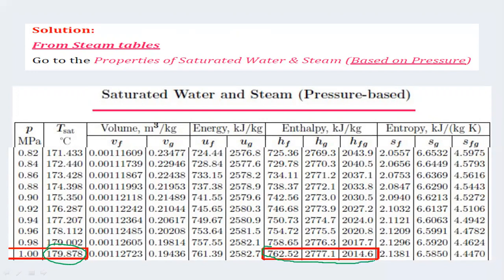These are the enthalpy values, specific enthalpy values. Remember these specific enthalpy values which you are taking out. It is for what conditions? It is for kilojoules per kg. For every kg, these are the values. But in our question, what he has said, you have to calculate the enthalpies for how much mass? 3 kgs. So once you get the values of enthalpy, you have to multiply it to the total mass and get the respective answer. So let us see how we can find these things.